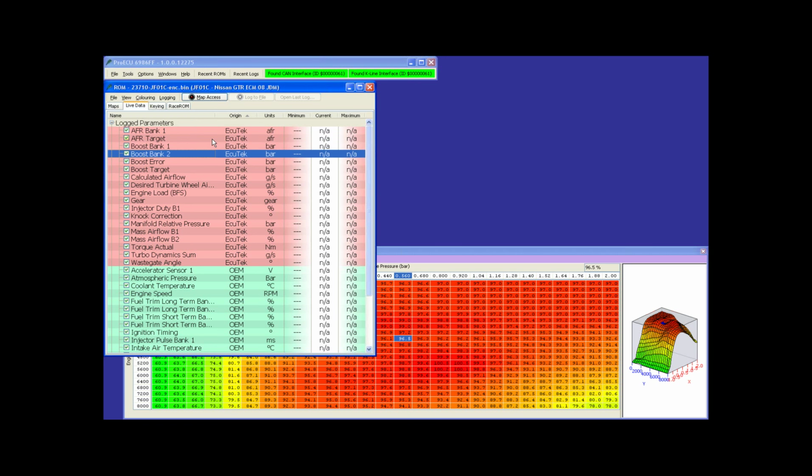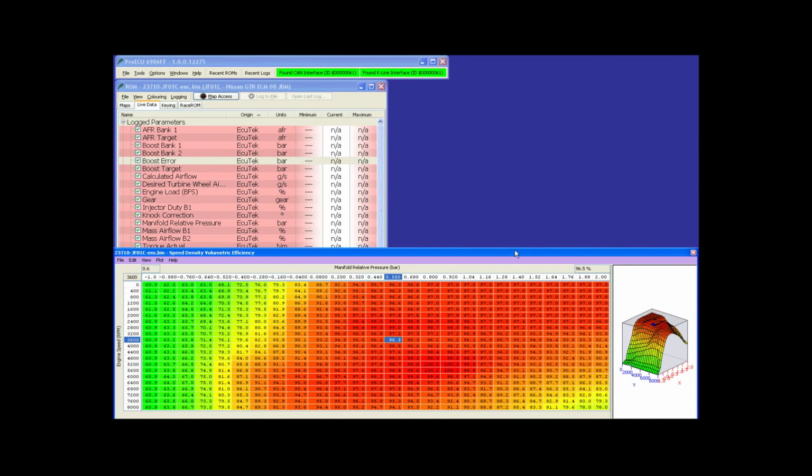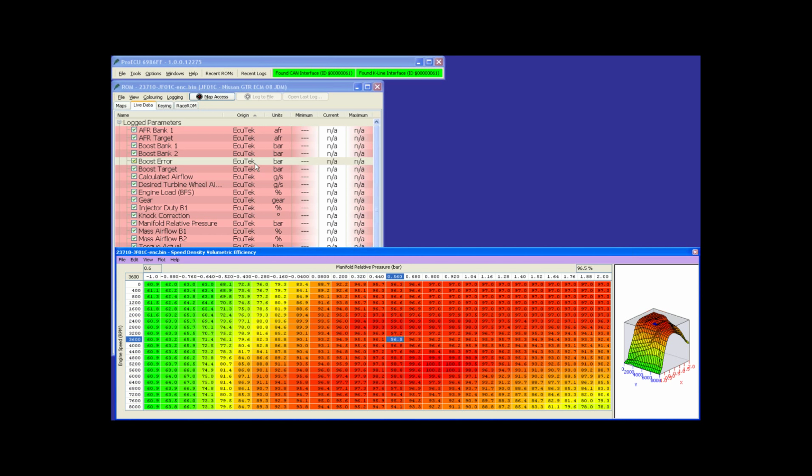We name them as boost sensors. They're pre-throttle, so they never show manifold depression. Boost error shows, again, as mentioned earlier, you may well have a target boost pressure of 2.2 bar, but you might only be getting 2 bar. The reason you're only getting 2 bar and your boost error says 0 is probably from a compensation factor.